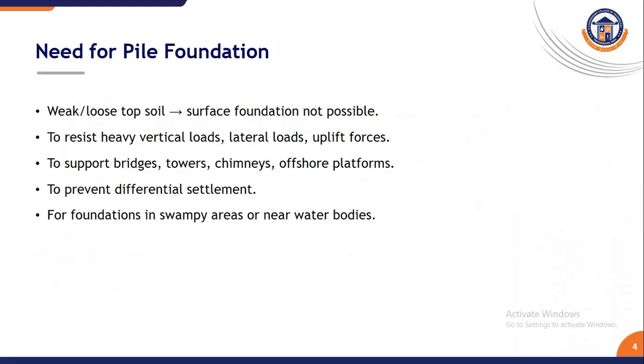Next one is the need for pile foundation. Here, pile foundations are necessary when shallow foundations are not possible due to weak or loose soil at the surface. They help resist not just vertical loads but also lateral loads and uplift forces, making them suitable for tall or slender structures. For example, an offshore oil platform in the ocean stands firmly only because of piles driven deep into the seabed. Right?